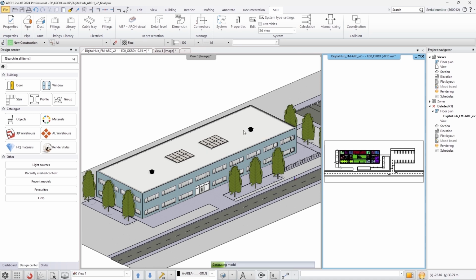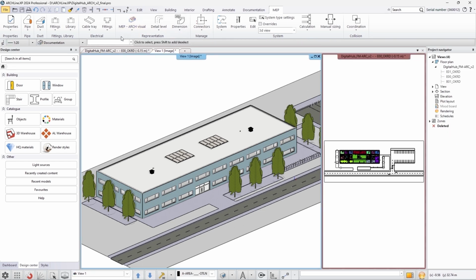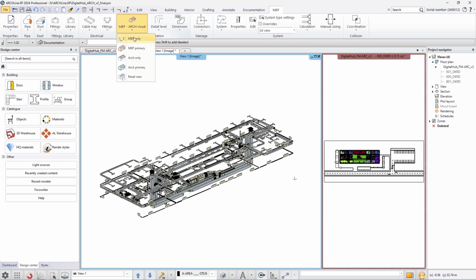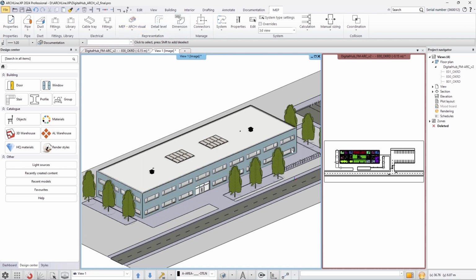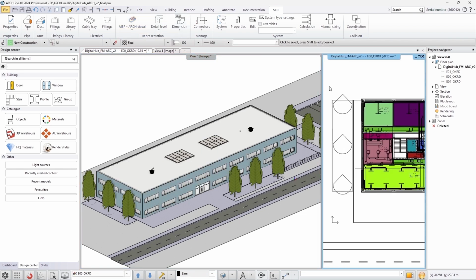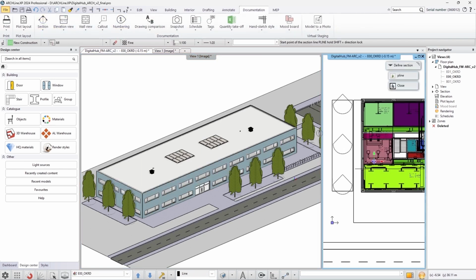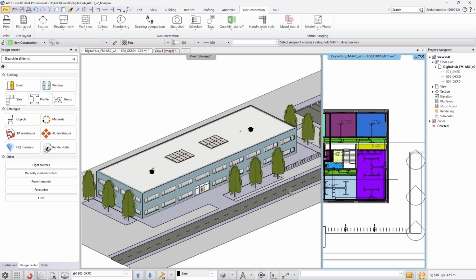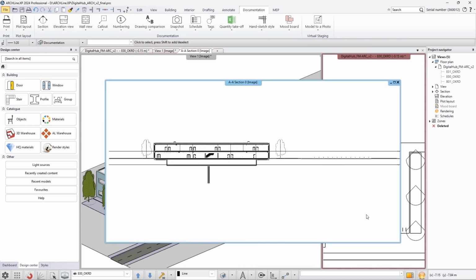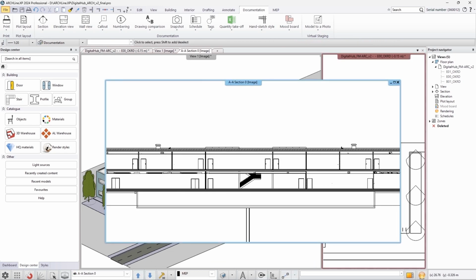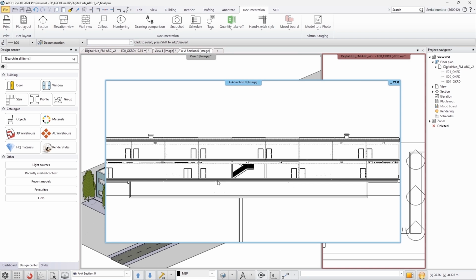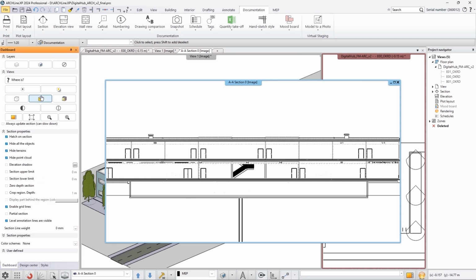Second step. Combination of the architectural 3D model and the MEP model. Data transfer between BIM programs is possible using the IFC format. Import the MEP plans as an external reference for the building model in several steps: heating, air conditioning, water pipes. The 3D model of MEP services then allows you to plan all MEP services within the architectural and structural constraints of the building.